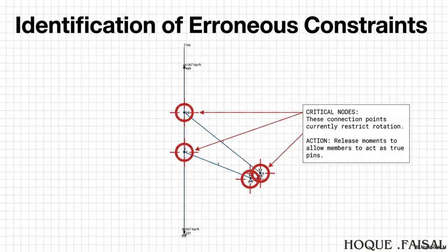You start locking things down, you go to a support node, you click fixed, you run it again. Okay, now it runs, I get a result. You constrain the model until the error message goes away. You've nailed it. You torture the data until it confesses. But by over-constraining it, by locking down those nodes just to get a result, you created a model that is stable math, but it's fake physics.